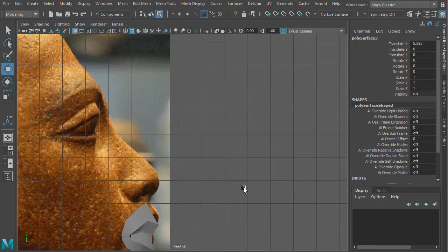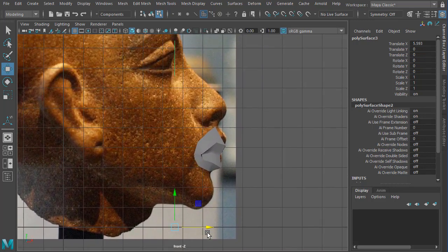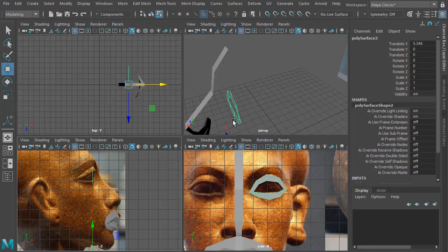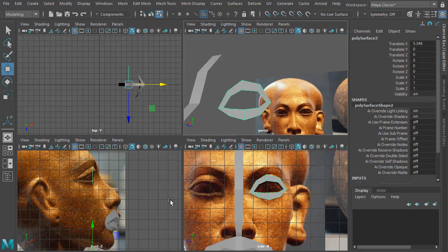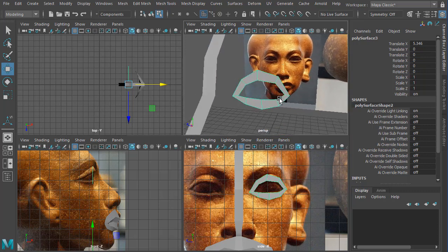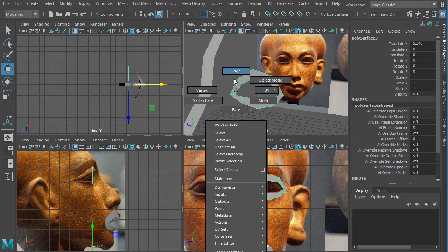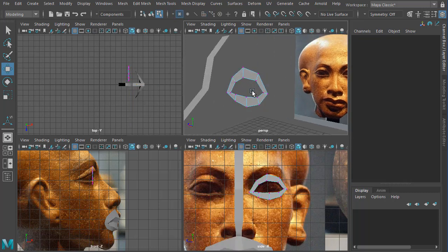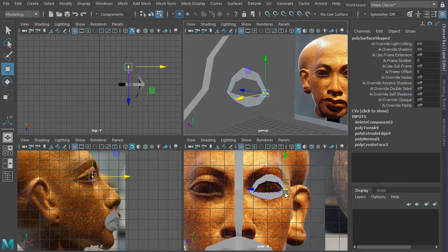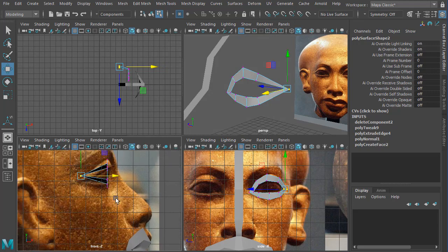Okay, there we go. So we have it right there. So that would be the center area. And now I will have to look at the front view and the side view, and then I will have to adjust them here. So let me just go to the vertices, and these two are in the back here, which needs to come all the way till here. So I'll go ahead and push this back, maybe slightly down.